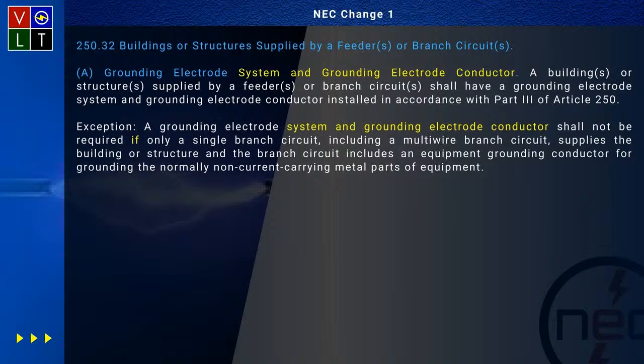Now, when you go over to that other building or structure, 250.32(B) ties in with this, and it basically tells you that the neutral has to be isolated over there. Right. Okay. And me personally, I would just take a number 4 right out of the concrete-encased electrode and hit the panel. You're done. That's what I do. You can make it complicated, but don't worry, because that'll be coming up in 250.66. It gives a little more explanation, from when I made that substantiation trying to explain that. So to me, this is a good change.